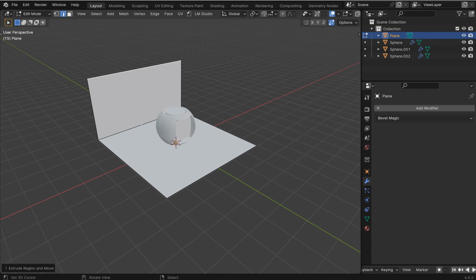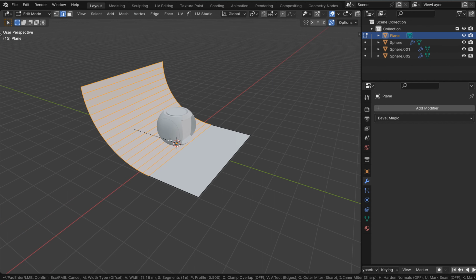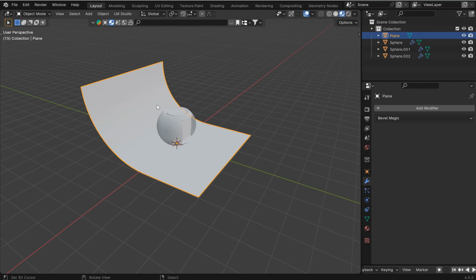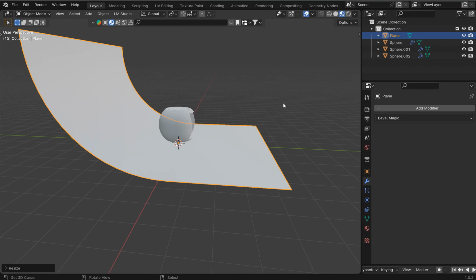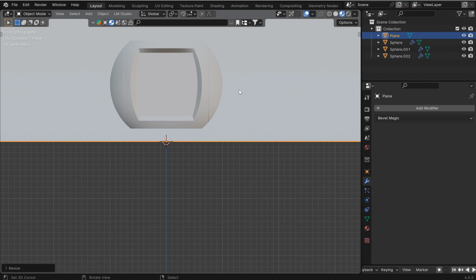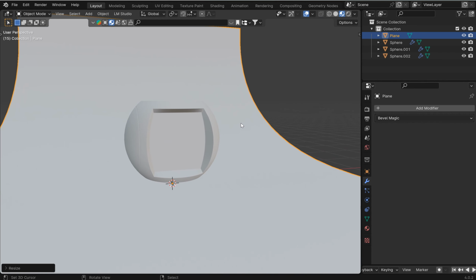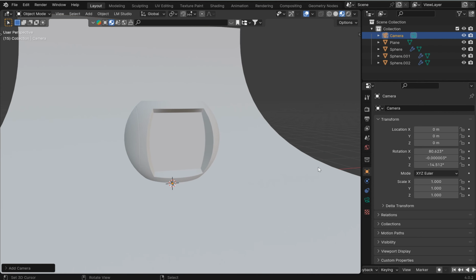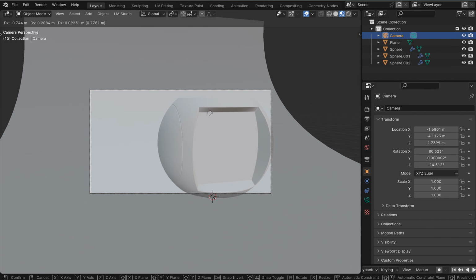Then just make a little plane, grab the spine here, and I'm just going to bevel that and then add some segments and run the segments pretty close to the top and shade it smooth and scale it. Then we can take up a top view, maybe something like that. Throw in a camera, Control-Alt-0, kind of bring that in.